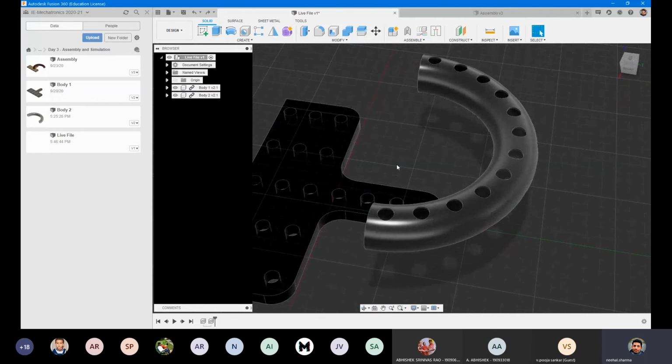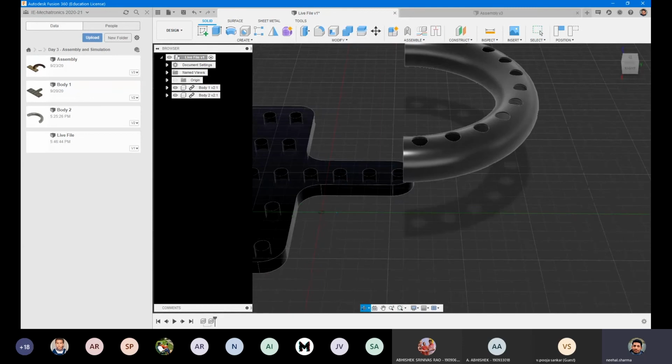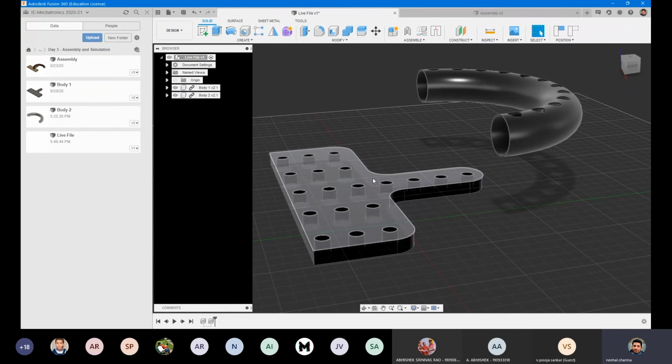Now that you've imported, or you could say gotten both the parts, what we need to do now is apply constraints. Once again, you have constraints in sketching, and you have constraints in assembly also, because technically speaking, these two parts are still unconstrained, just floating in free space. And for assembly, obviously, it's like when you draw a free body diagram in physics, right? It's customary to include a reference point, or in other words, something like a ground reference or a ground link.